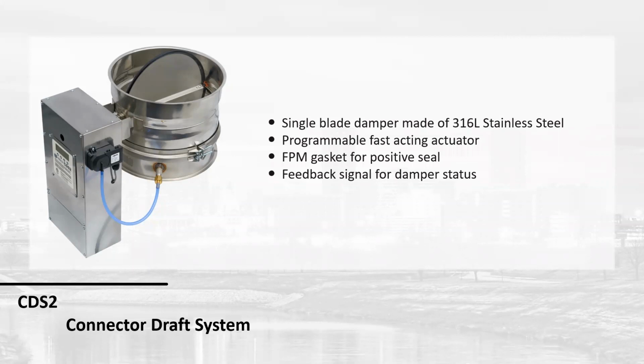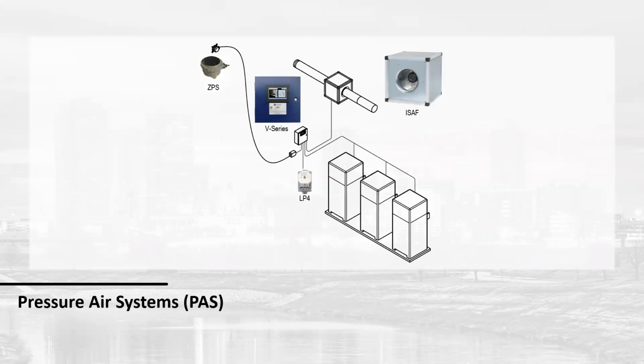Yeah. Then we have another question from Eric Polito, asking if you could show the combustion air fan diagram again. Sure. So this is just a generic conceptual diagram. Obviously, this pipe would go through the wall. The controller and the sensor here would be in the room. This would be an outdoor sensor. So we're basically just trying to match the atmosphere, so that the room always has atmospheric conditions to pull from. But there's several variations, Eric, that we can show you if you have a specific job.